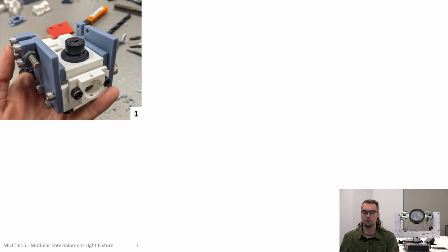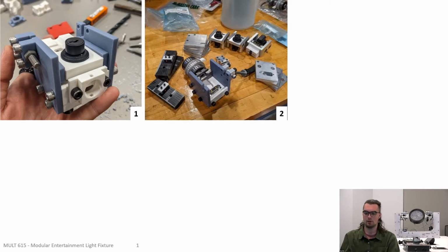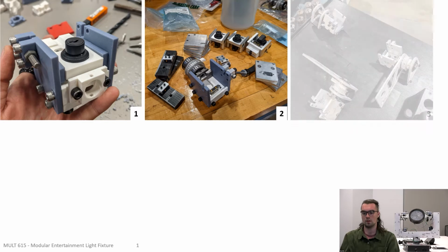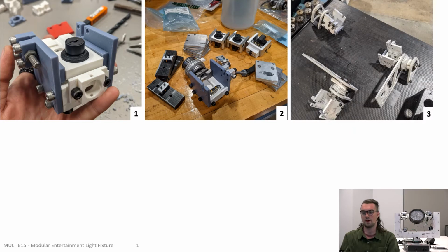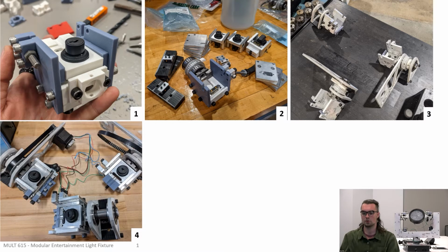As Alicia previously discussed, the joint was developed in 2 CAD versions that we called version 1 and version 1.5. From these, version 1.5, seen here in the upper left, was tested and modified through 2 rapid prototype versions made on 3D printers in the VCU makers studios. Then the final joint assembly was constructed from aluminum, steel, and polycarbonate in the VCU maker garage. The full construction of the light's frame components, including the yoke and base, was designed in 1 CAD version, which was then machined to fit the existing lights.